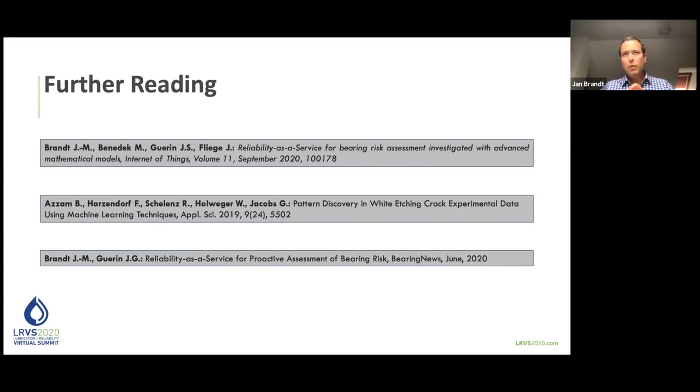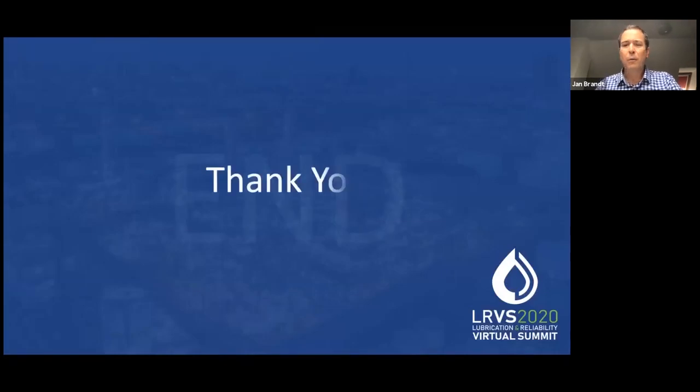Important, the main message is that we look at the risk of the lubricant before damage occurs, and this has been validated and applied. So this allows you to take measures right when the lubricant, for example, is shipped to a different location. Is there water ingress or other contaminants coming in? How's the risk of my lubricant? And also at the early stages of operation, when the lubricant has been filled and replaced after washing of the application. How's the risk after early running? Has that changed? There's a lot of quality control, but also it's very proactive in saying, if you have a certain condition with electrical charges that could occur, you run into this risk. And that went through, it's like 20 minutes on the button.